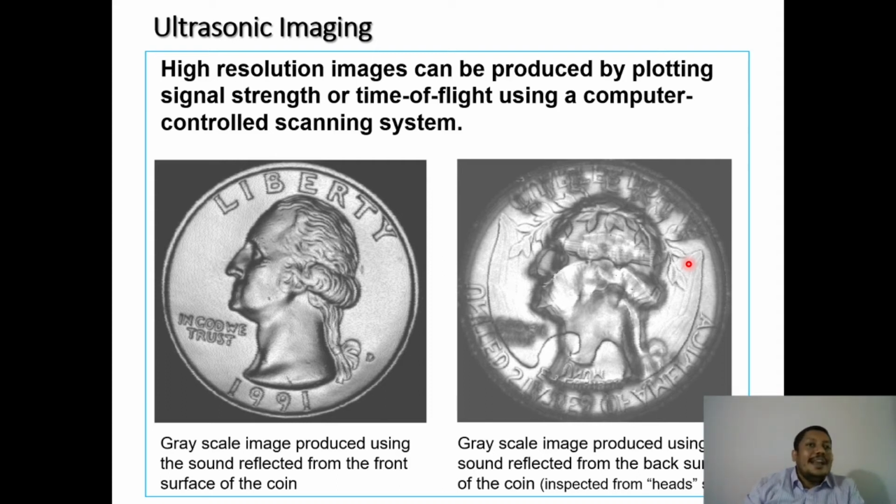Repair welding normally takes 10 to 20 times, the cost of repair welding will be 10 to 20 times higher than that of a normal weld. Now think of a condition where I can make a weld without any defects. No NDT techniques are required, no other processing is required. But I have to control my weld process monitoring parameters at the same time as welding is taking place.